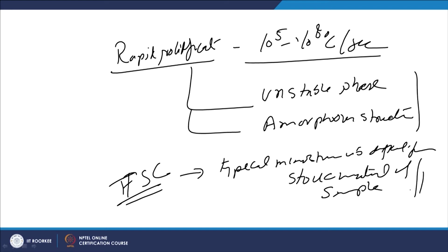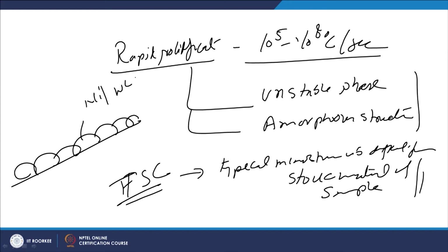So, this different microstructure makes it very difficult to recognize which constituent belongs to which type of particle. Like say, in the coating we have a large number of splats deposited like this. So, there can be nickel, tungsten carbide, chromium carbide, boron, silicon carbide, etc. So, it is very difficult in flame spray coatings to identify which constituents belong to which particle.